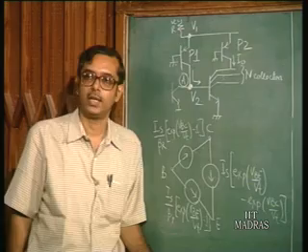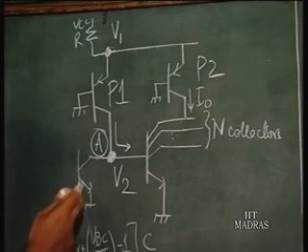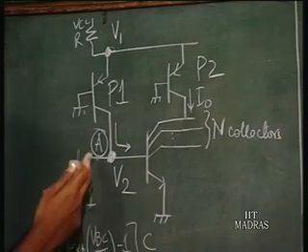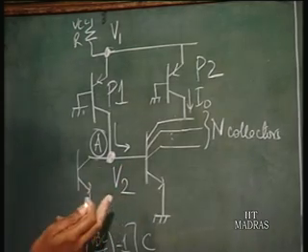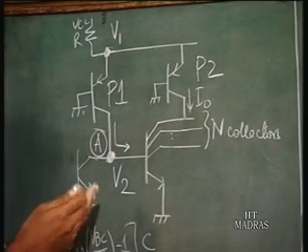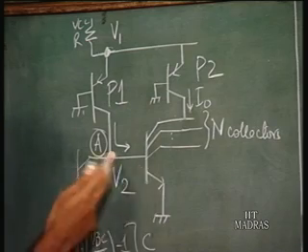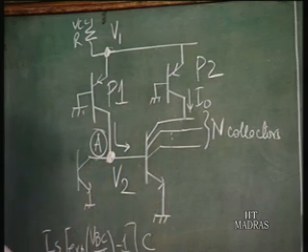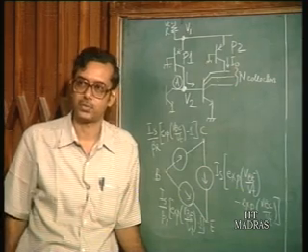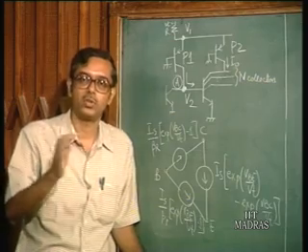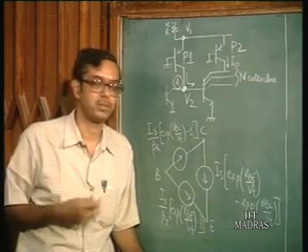Okay. All right, because of the 0.2 volts when the transistor goes to saturation at a node, this voltage cannot exceed about 0.7 or slightly more, because this is the base voltage of this transistor and it cannot exceed a certain value. So, the voltage swings are going to be much lower.